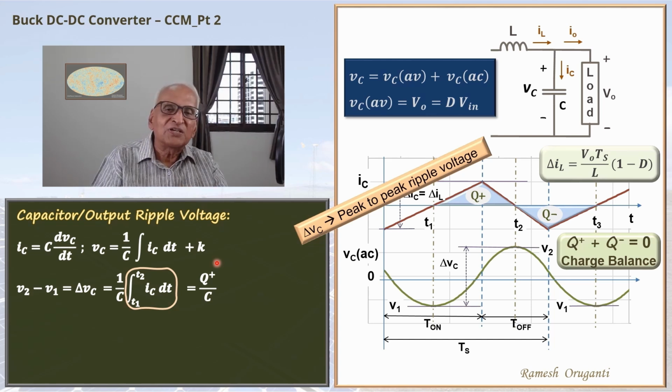So we are acknowledging that the output voltage is not pure DC, but for inductor current calculation purposes, assuming that the capacitor voltage is constant is good enough. The ripple voltage is a secondary effect. The magnitude of the ripple voltage is quite small, less than 2%, less than 1%, even less in many cases. The ripple voltage is small enough that it does not affect the previous results. So our assumption of the output voltage being constant to determine the inductor current is perfectly all right.